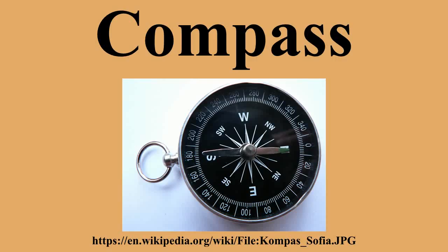These directions may be different if there is a crosswind or tidal current. GPS compasses share the main advantages of gyrocompasses. They determine true north, as opposed to magnetic north, and they are unaffected by perturbations of the Earth's magnetic field. Additionally, compared with gyrocompasses, they are much cheaper. They work better in polar regions.